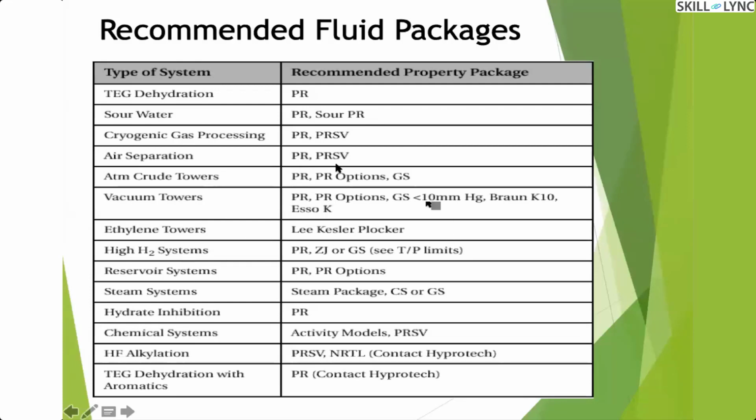This is just a general guideline, but you will have to be more specific when you are selecting the fluid package. Say when you have a glycol system, some of the simulations themselves will give you a warning when you select the wrong property package with the wrong selected component. So selecting proper fluid packages is very important. Only then will you have an accurate prediction of your vapor liquid fraction distribution. Yeah. So now let's move on to the next.